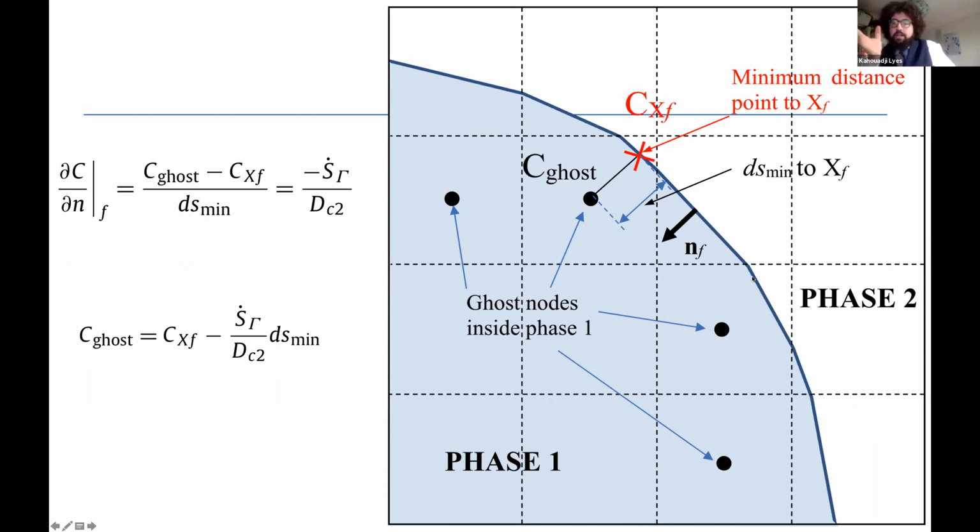It's really a numerical tuning. When two interfaces come very close, by a numerical criterion, we put it at something like 2% of the size of the grid cell, there is a local reconstruction of the interface, and a local redistribution of the surfactant at the pinch-off.